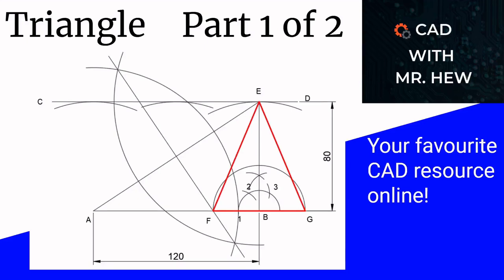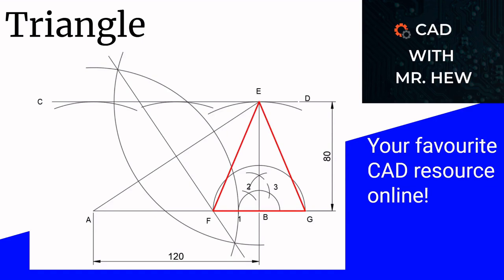This is part one of two videos covering the topic how to construct an isosceles triangle given the perimeter and the altitude. Welcome to CAD with Mr. Hugh. In today's video, we'll be looking at the construction of an isosceles triangle given the perimeter and the altitude.